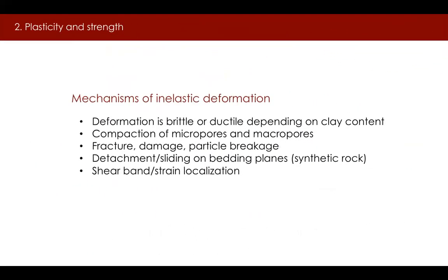The second part of my presentation revolves around plastic deformation and strength of transversely isotropic rocks. To motivate this presentation, it is important to note that shale generally contains clay minerals and organics. So we can expect either brittle or ductile inelastic deformation depending upon the clay and organic content.